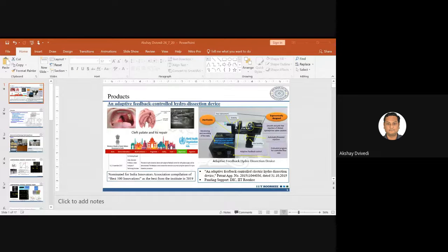And this rise of temperature will be evaporating the water part, only salt will be remaining. End result, you have a particular scenario where for a particular time being, there is excess of salt, and this basically alters the performance of the process. In certain cases, certain sludge comes out during this sparking, and that also creates something which is mentioned as a passivation layer.